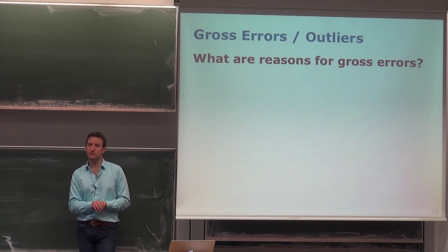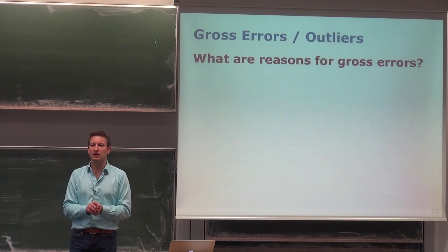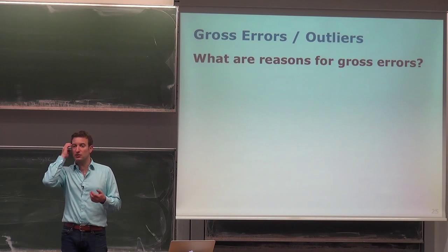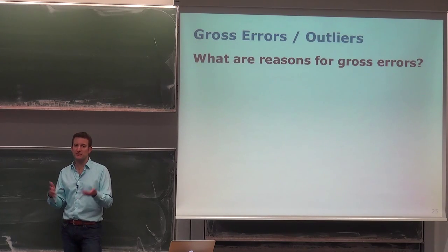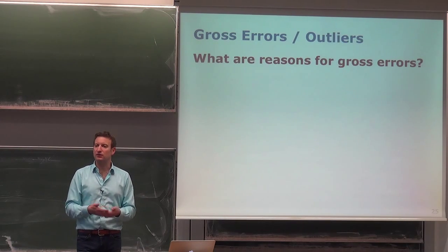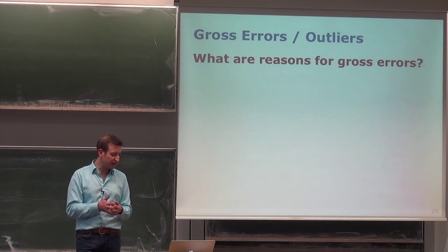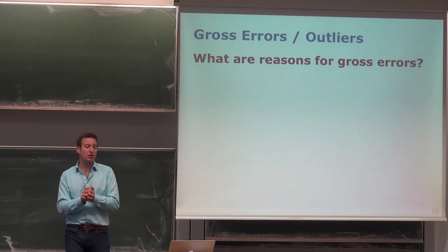It may also be that my feature descriptor is not expressive enough to separate two points which for us as humans look completely different, but from the feature descriptor point of view may look the same. So I may also get wrong data associations or wrong correspondences due to that. But this is the main source of error: wrong correspondences.